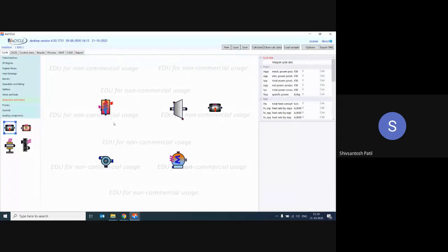Then I'll start the connection. Now just see the connection. Okay. Just see the connection. Here, from the boiler, you can see the outlet of the boiler goes to the turbine. So I have to just click here and drop that click. You have to click here and come with the next click to the next area. So you have to be in the click mode. Click and take it to this point. Okay. Keep your mouse button clicked and come to this port. Now this will send to the next. Click here, bottom. You can see the connection. Okay, please observe the connection.